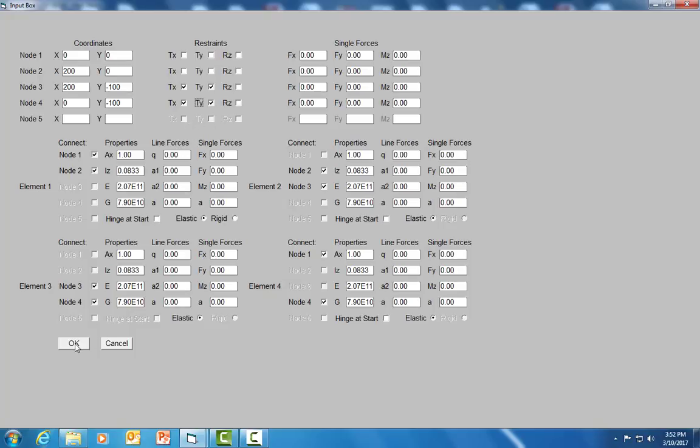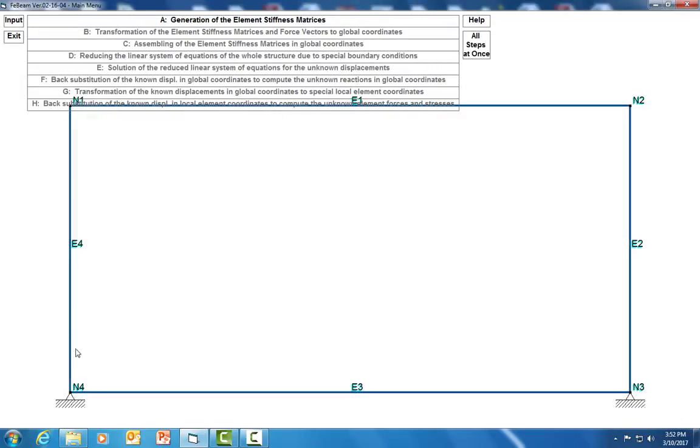So to show this, we see here, this is simply supported, named simply supported. So the whole structure can rotate here, but cannot move, and therefore cannot move here. So the warning is gone. We have now this fixed supported.